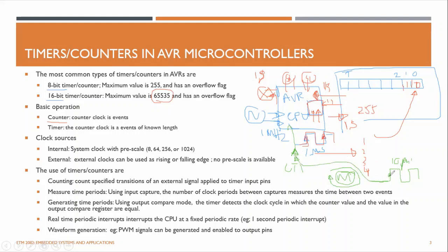So each and every pulse will update the counter register, right? When 10 pulses go, you know this value is now updated to 10. So you know it's one revolution. If it is 5, you know it's half a revolution. If it is 20, you know the motor has rotated two revolutions.